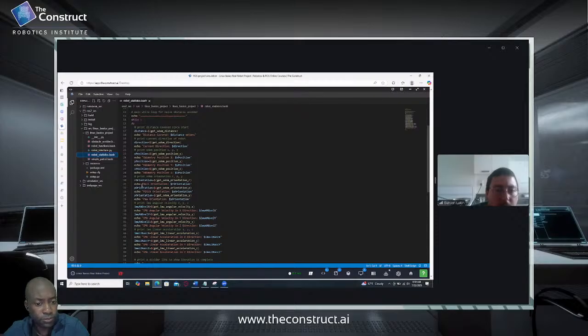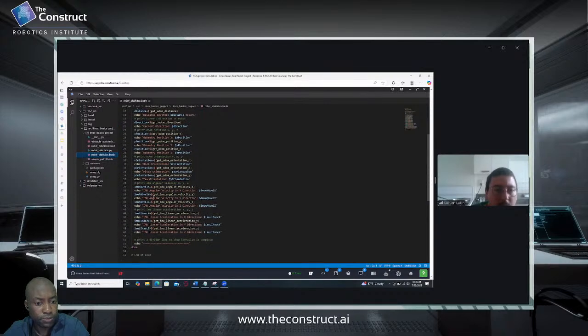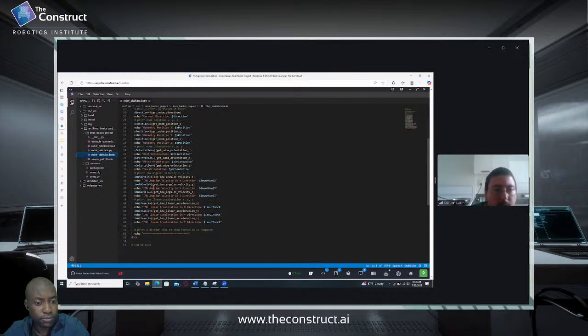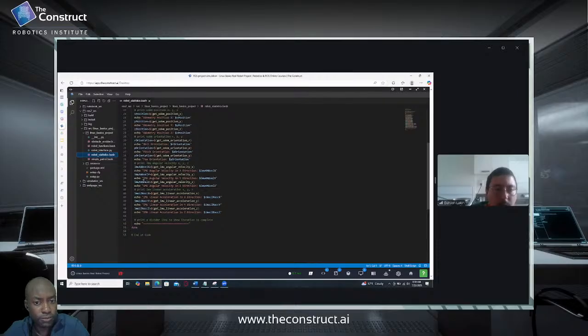So then the yaw, this is not too relevant for this, since we're moving in a 2D plane. This is more for an object that is floating in XYZ space, not just XY, but it's provided just because the robot could fall over, become unstable if on one wheel. And then the IMU, the inertial measurement unit, provides angular velocity, and linear acceleration is provided by the IMU as well.